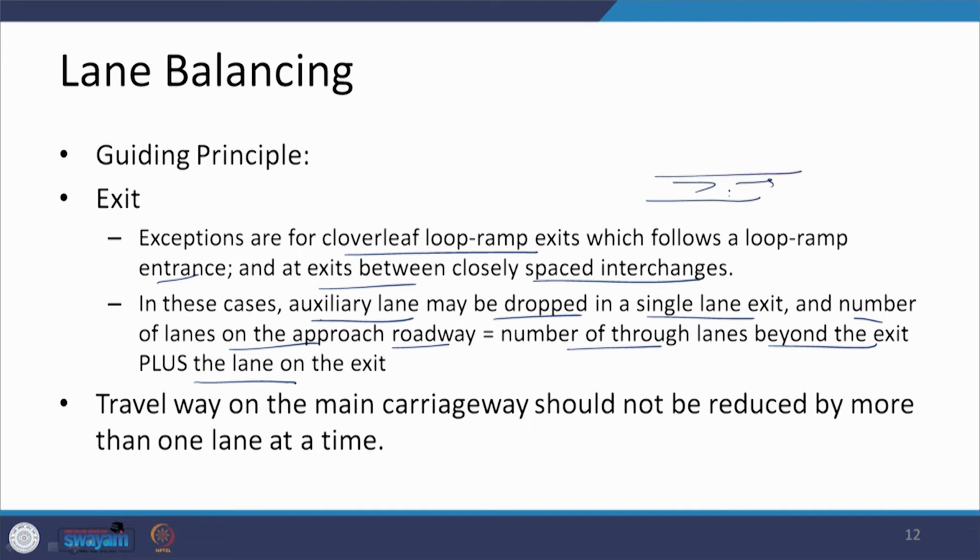So, this is what we are saying, and then there is an exit in this direction. Accordingly we are considering that the travel way on the main carriageway should not be reduced by more than one lane at a time. So, this is also another guiding principle.